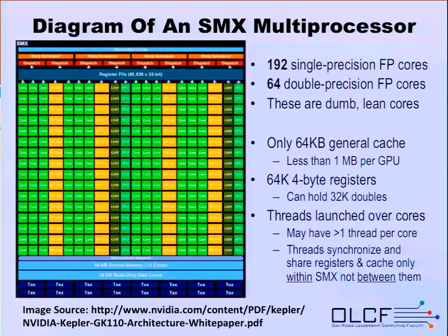There's also a pretty healthy register file, but it's used by the entire multiprocessor. So there's about 32 values if you're in double precision that you can store in register across the whole device. But remember, you have at least 64 cores. If you're in single precision, you have a lot more. So that just says, again, you have to be careful with what you put in register, how you use the cache, and what your algorithm's doing locally.